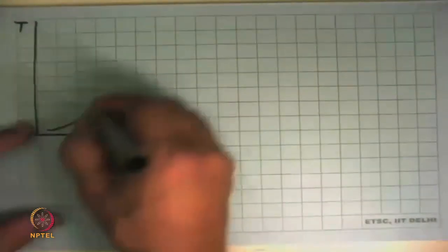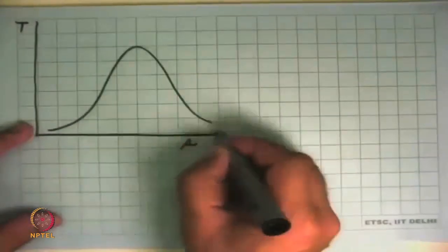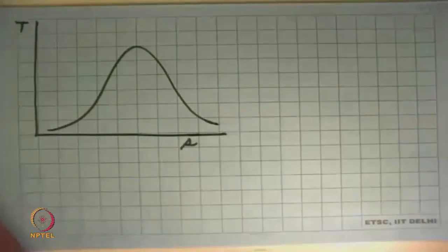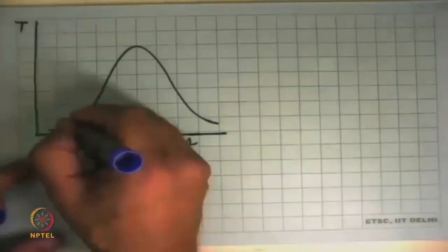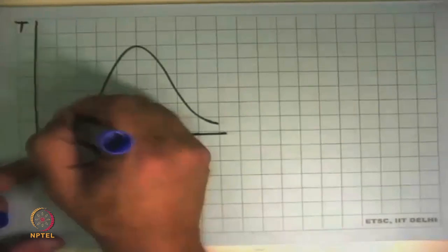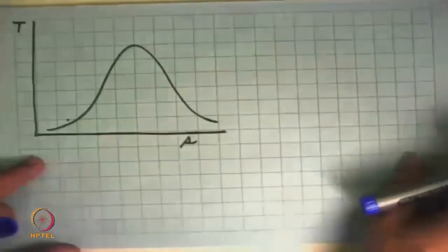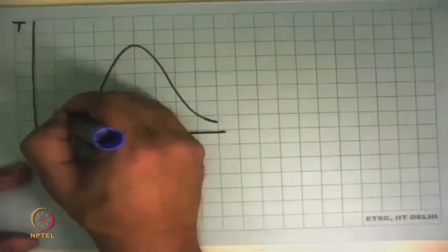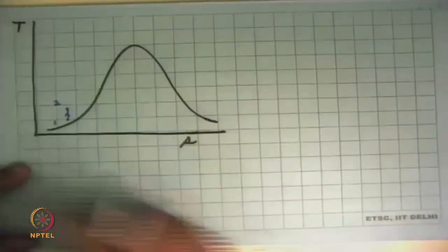Okay, now let's look at TS diagram. In the second pump, we are pumping water at ambient conditions. And we know that ambient water is slightly compressed liquid, and when we compress it, the pressure goes up, and in the ideal case, it is adiabatic, and if it were reversible, it will go up over there, and this will be 1 to 2.